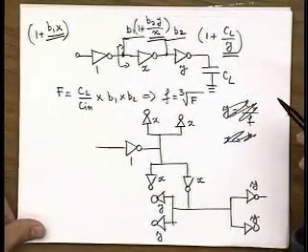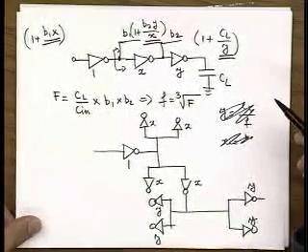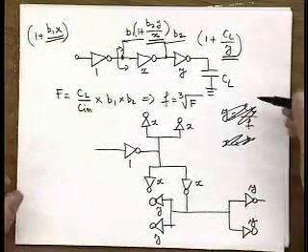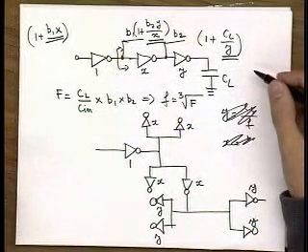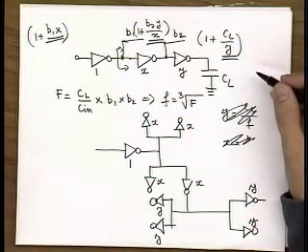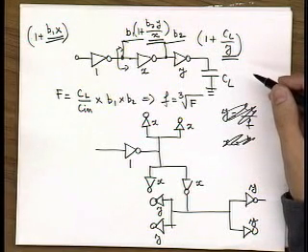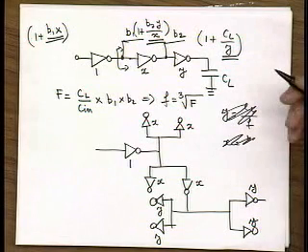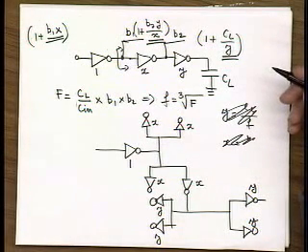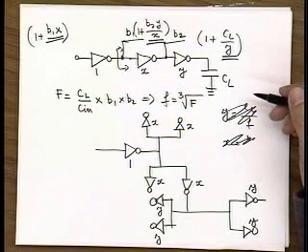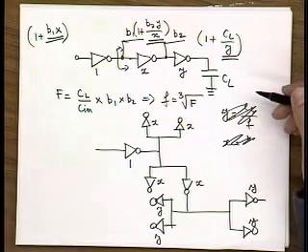The next thing will be to validate this in HSpice. In order to do so, you will need an estimate of TP0 and gamma. In the posting that we will have online on Tuesday, you will have a clearly outlined methodology along with the SPICE deck for how to estimate TP0 and gamma. For the homework problem that we will post today, you can either calibrate your TP0 and gamma for our technology by yourself, or you can just wait until Saturday, understand the methodology, and use the numbers that will be given in the hints and tips.